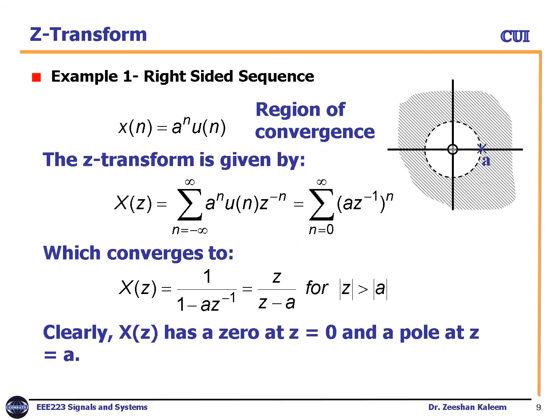Now let's take an example to discuss how we can calculate the Z transform. This is called a right-sided sequence. What is meant by a right-sided sequence? It means that the region of convergence lies outside the circle, on the right side of the unit circle. So let's prove this by an example. For example, the given signal is x[n] = a^n u[n]. Here u[n] means that it is right-sided, because u[n] is positive for n ≥ 0.